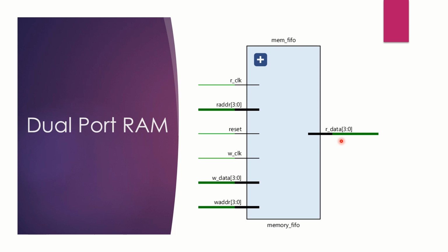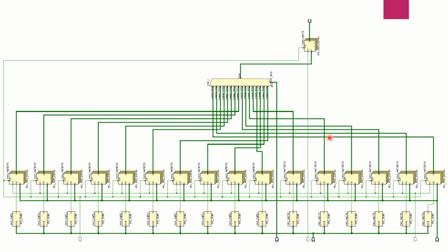Depending upon the System Verilog coding, this diagram shows the inside of the FIFO memory block. The first layer of blocks take write address as the input and generate chip enable signal for the corresponding address. For example, if the write address pointer points to the 0th address, then this block will generate the chip enable signal and enable all the flops residing at that address. These flops will then take write data as the input and store it.